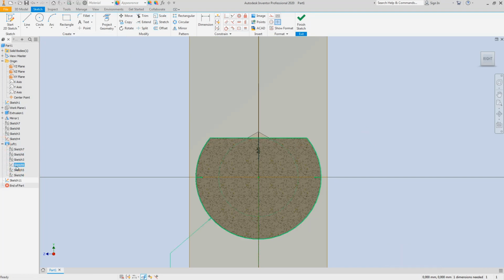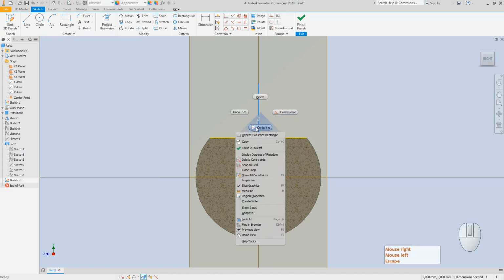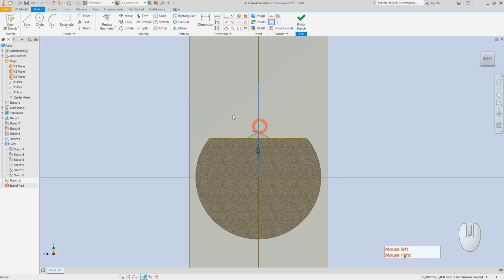For this, I'm going to use, open the sketch 9, have this line with this, close the sketch, and I will just add, first of all, I have just created a center line, convert this line to center line with a box, and this point is having the 39 millimeter distance from the center line, and it is 4 millimeter in height.